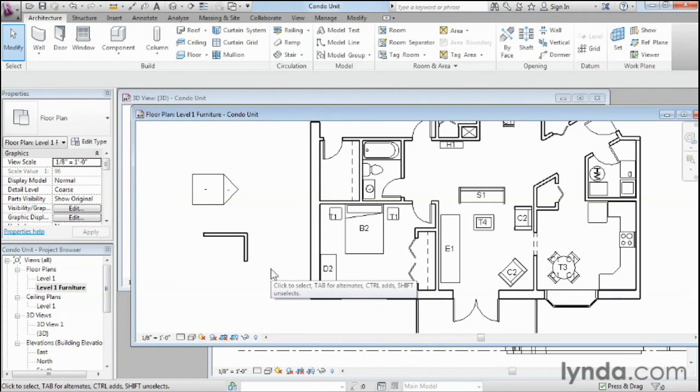You'll get similar behavior when you select an object or when you pre-highlight an object. So in AutoCAD, you can put your mouse over an object and it will pre-highlight. You can do the same thing here in Revit. Notice that the tooltip appears on screen. Now that's going to go away after a second or two, but notice down in the status bar, that same message still appears. It says walls, basic wall, interior 4 7/8 in this case.